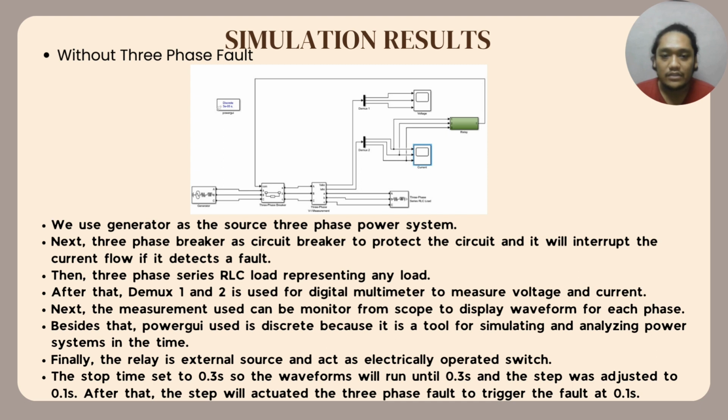The stop time is set to 0.3 second so the waveform will run until 0.3 second, and the step was adjusted to 0.1 second. After that, the step will activate the three-phase fault to trigger the fault at 0.1 second.